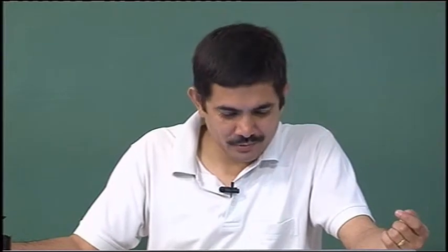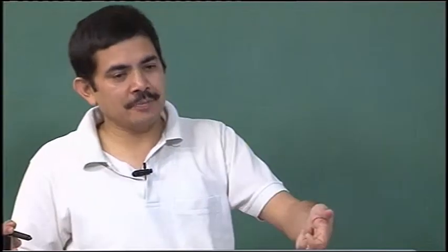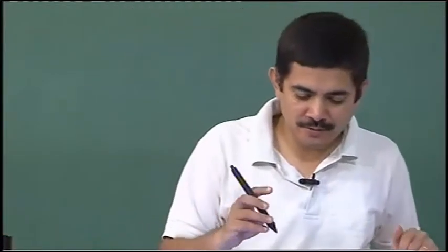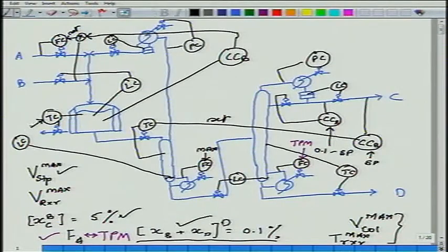Okay, what was I saying? Yeah, so you are jacking up the throughput and temperature becomes max. When temperature becomes max, you still need to control the level. What do you do? You start adjusting the concentration of limiting reactant. I want the concentration of limiting reactant to be small, let us say 2%, 3%, 5%, but now if I still want throughput to increase, the set point, the limiting reactant concentration inside the reactor is increased from 5% to maybe 10%. That will give me further increase in throughput. Yes or no?